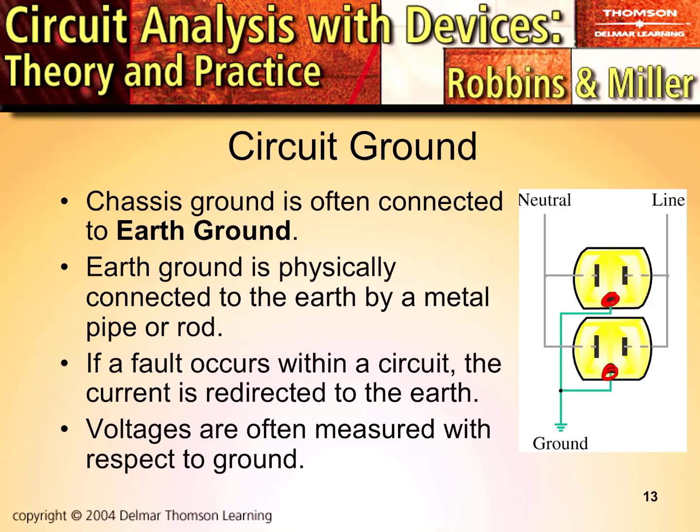Remember in the lab, day one, when we took the center prong of a plug on your power supply and used our ohm meter to measure the resistance between it and its chassis, its cover, the screw on that cover. We found 0 ohms of resistance, a short circuit to that cover.